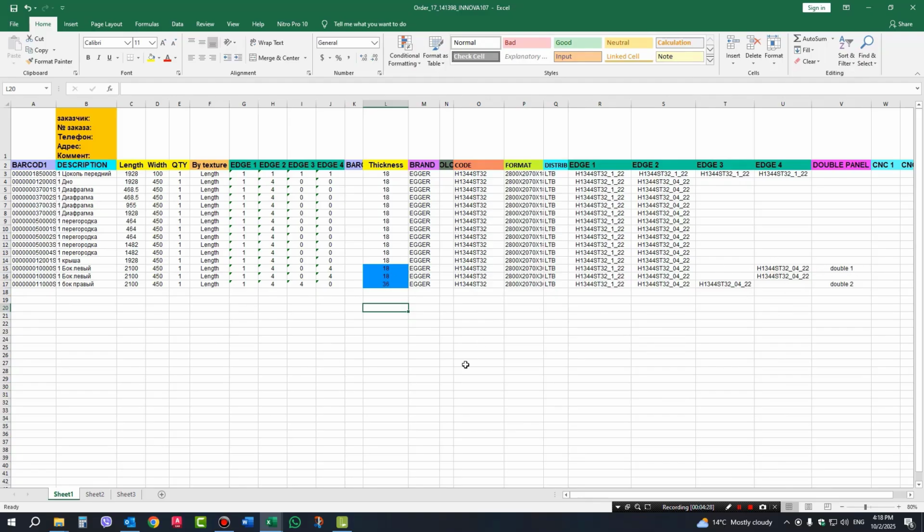But now we also need to, in addition to what we have done, know how we can edge band it. Well, since we're making the thickening up to 36 millimeters, that means we need 1 or 2, 42. 42 is the width of the edge band, 2 is the thickness. Yes, then I suppose it should say 2 here, 2 here as well, 2 here, 2, and 2 here as well. So edge banding on all 4 sides, that means on every side all around.